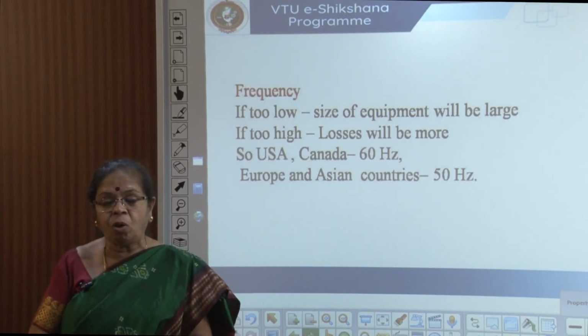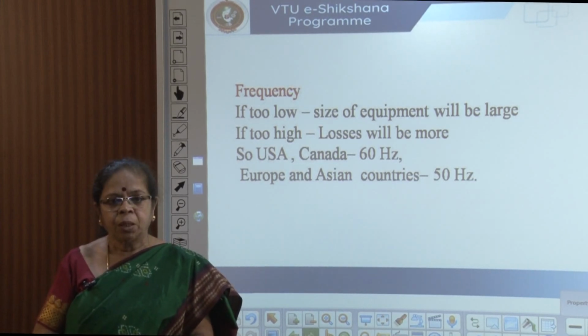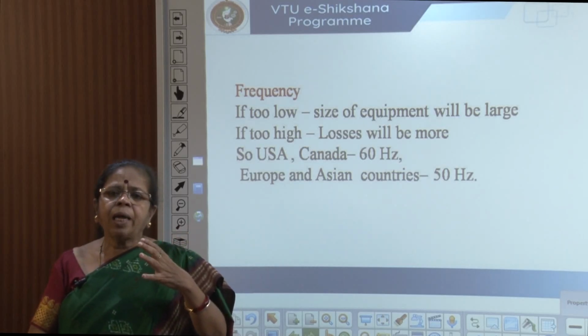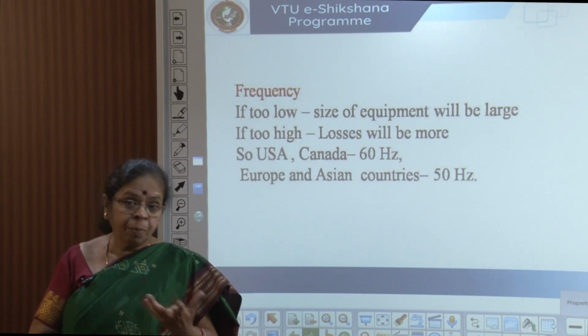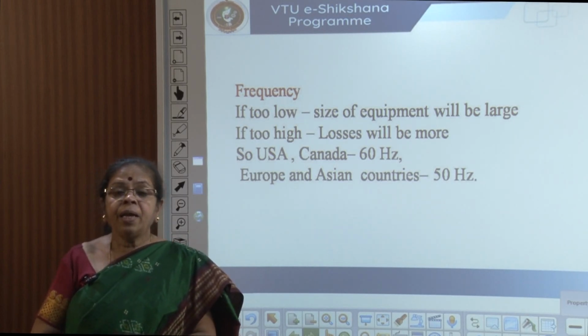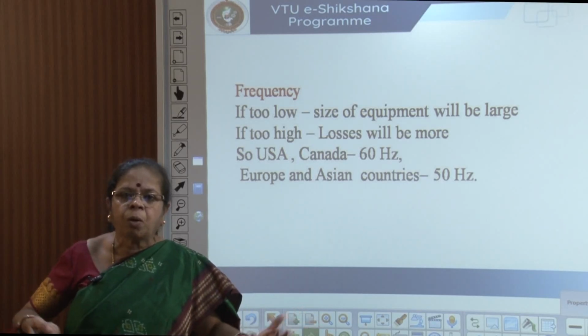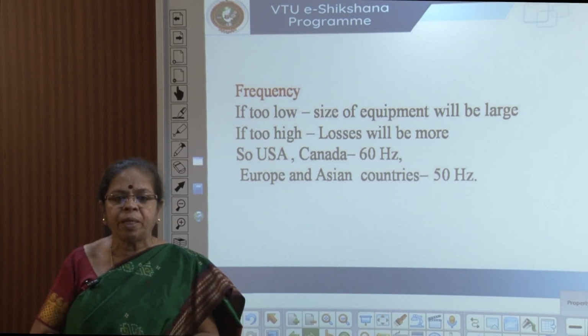You have seen the iron losses, they all depend on the frequency. So, if I operate the system at high frequencies, I will have to compromise on the efficiency, right? That will become very costly. And if I operate at very low frequencies, the size of the equipment required will be very large. That again becomes expensive because I need more material.